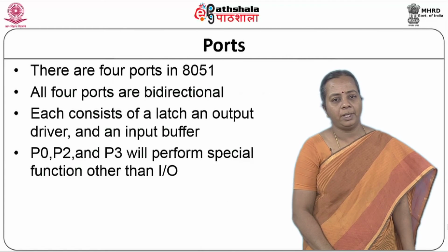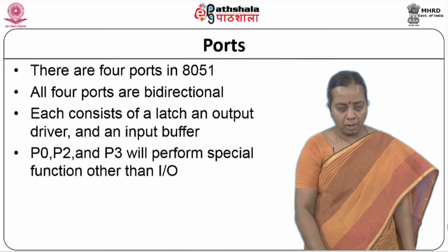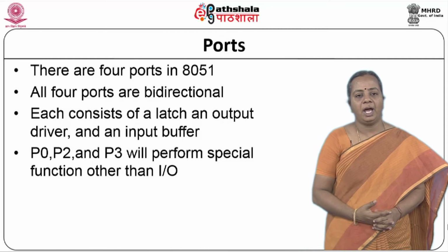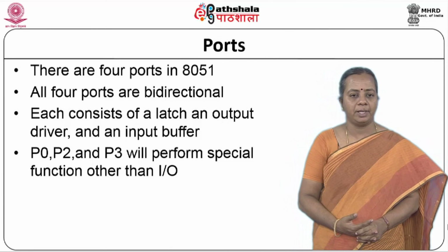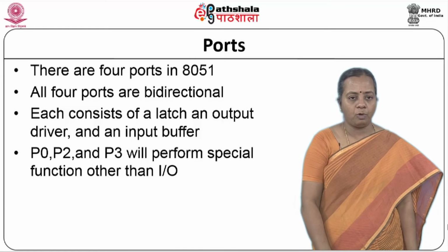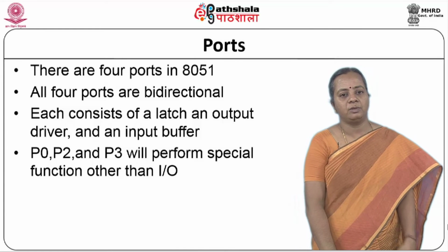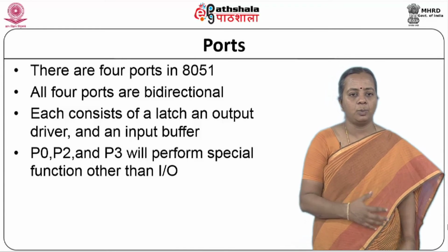Next we will be covering the ports. When I look at the ports, we have 4 ports in the 8051, as we have seen in the pin diagram itself. Those 4 ports can be used for inputting data as well as outputting data.